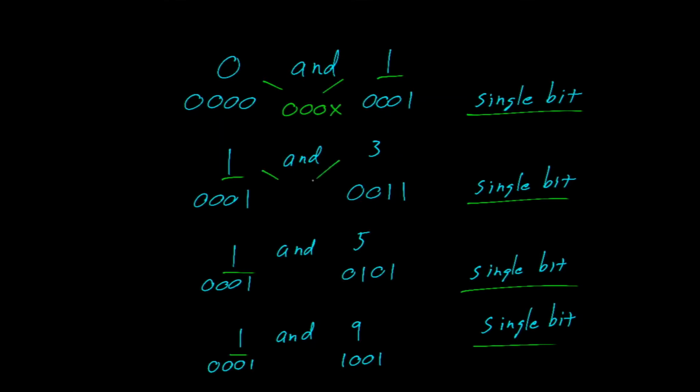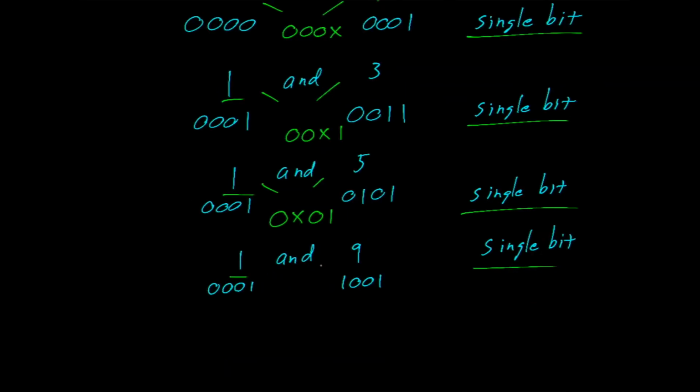Likewise, if the circuit was to respond to minterms 1 and 3, you could build the circuit as D0, C0, we don't care about B, and then A. 1 and 5, it would be D0, we don't care what C does, it would be B0 and then A. And finally, if that circuit should respond to minterms 1 and 9, we wouldn't be interested in D, but we would look for conditions where it's C0, B0, and then the last one is A.